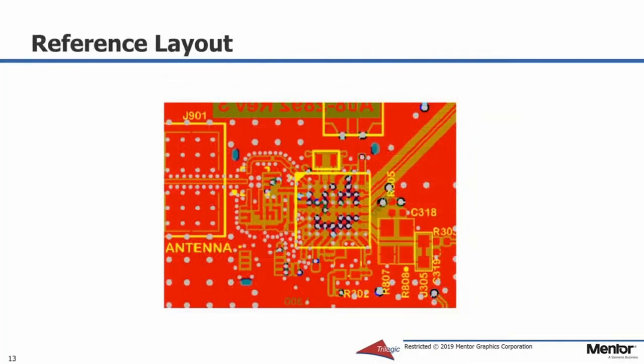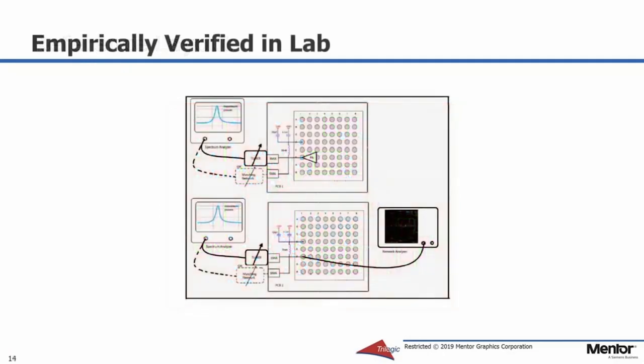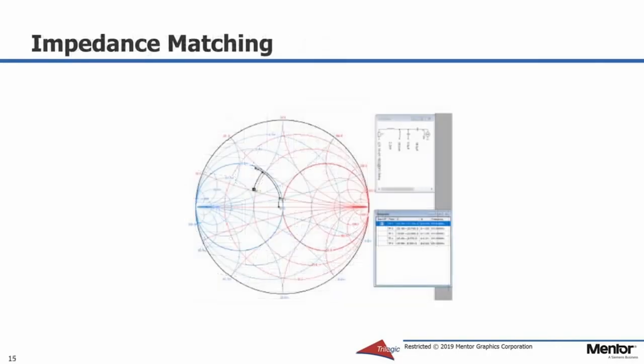Perhaps most important is a reference layout of all copper layers. This should be viewed as the golden rule when in doubt. All constraints should be configured with the end goal of producing copper layers as close to the reference example as possible. The manufacturer's app note will often include data collected analytically or empirically that shows important design and performance characteristics.